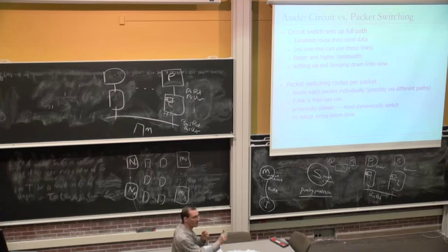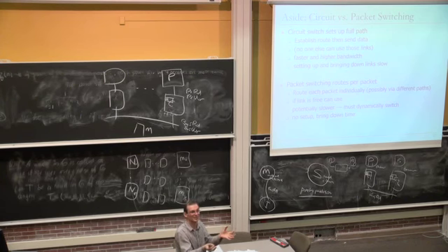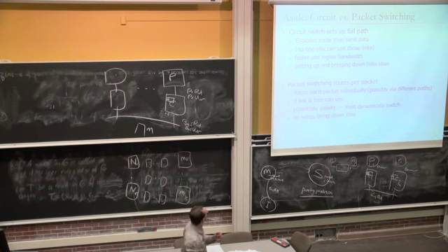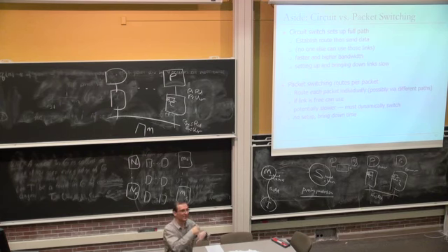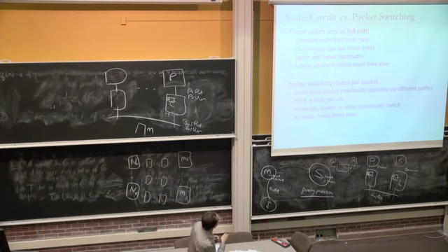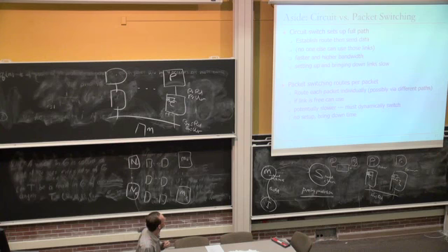It just sets up the path, if you will. You can think of this as reconfigurable logic a little bit, right? You reconfigured your muxes such that it sends the data to the right place early on. That's essentially what's going on. You're configuring your route early on before you send the message. That's why it's faster and higher bandwidth. But setting up and bringing down requires some protocol, right?